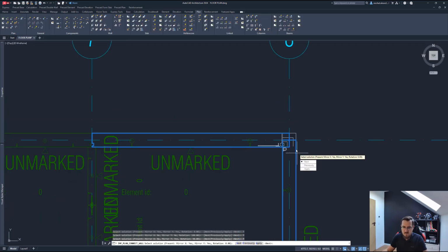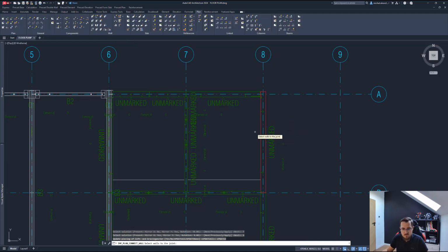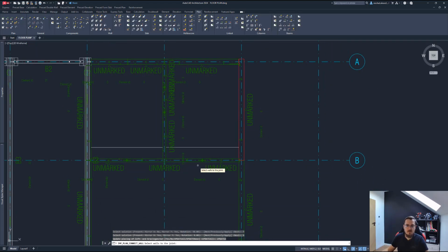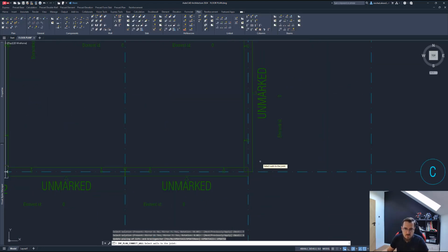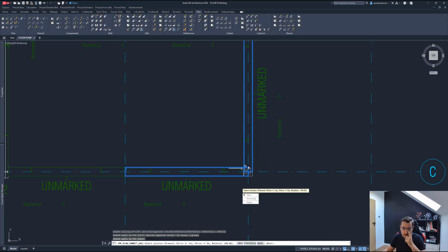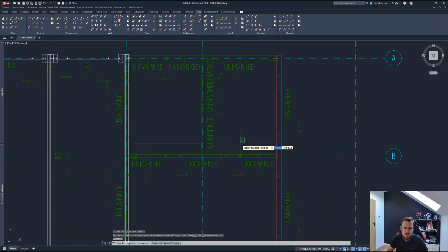So let's make the vertical wall here, vertical in view, the longer one. And let's accept that and update all. What happened now, as you can see, is this element got red. It got extended, and it got extended enough that it's too big now to be lifted by the erection crew, or it exceeds our limits in the software. I also select this corner, and I'll apply this particular extension, accept that, remove the auxiliary lines.